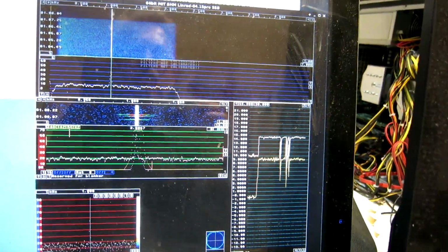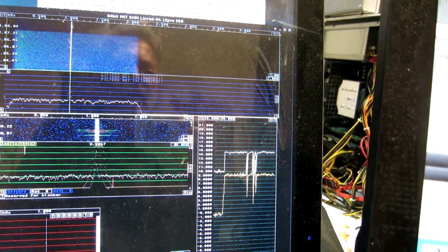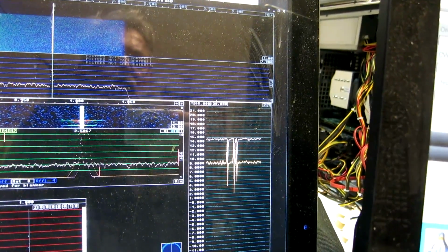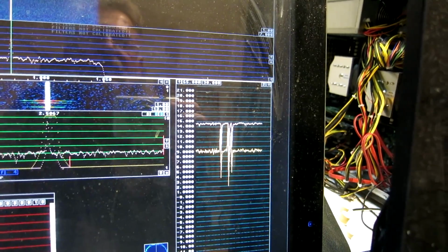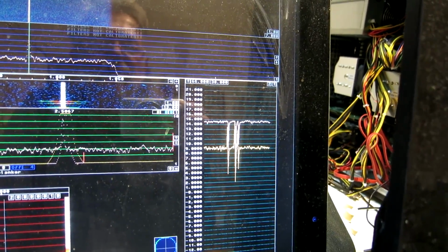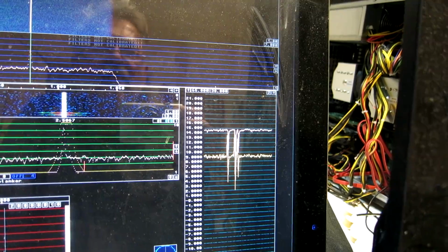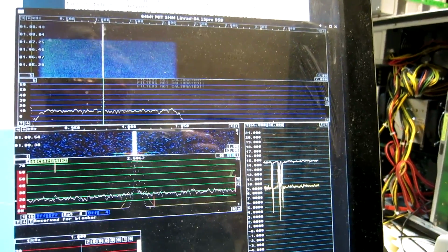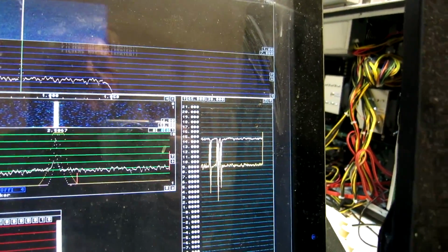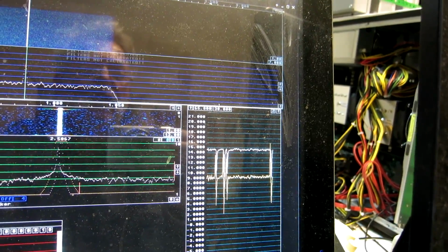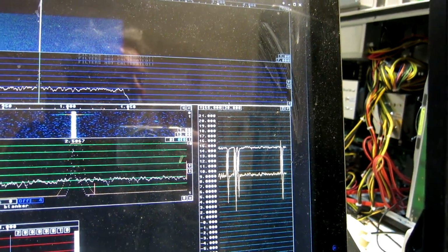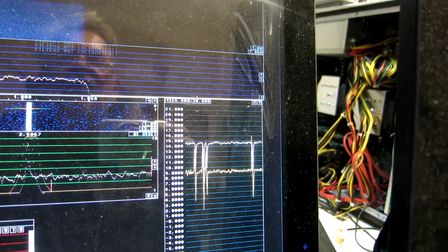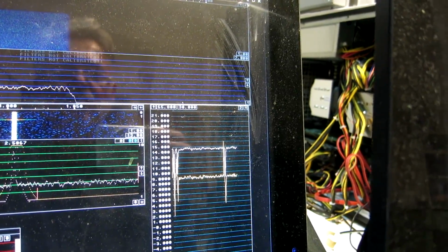Well, there was an easy way of bringing up the signal level. I reduced the attenuation in front of this unit by 10 dB nominally. Looks like 9 dB here. So the signal to noise ratio is 9 dB higher, and then the signal is also 9 dB higher. And I switch on that medium wave, which is now 9 dB above those plus 2 dBm I was reading, means plus 11. And as you see, it doesn't affect signal to noise ratio.